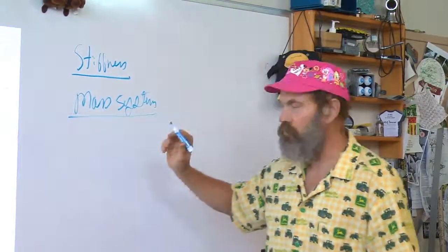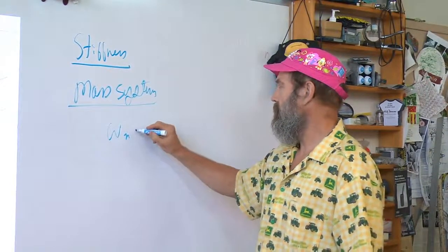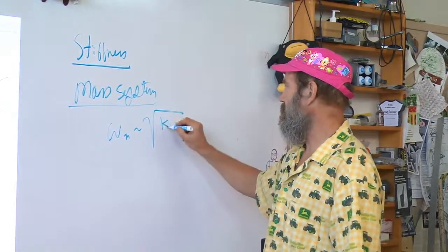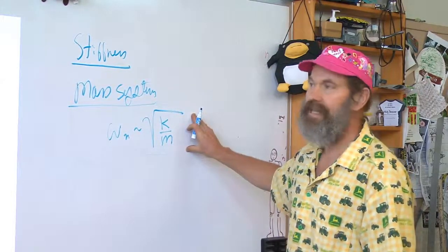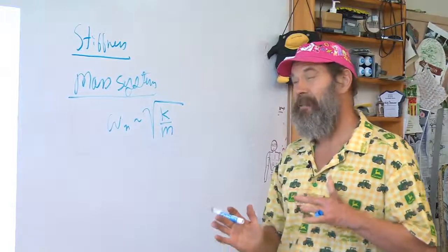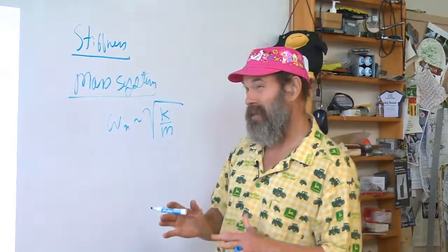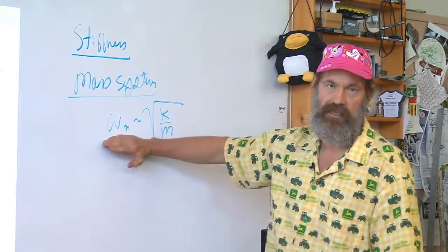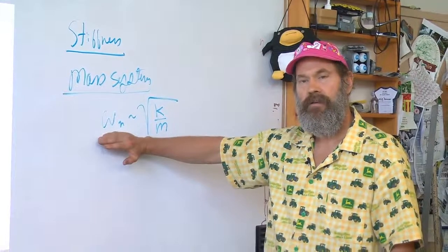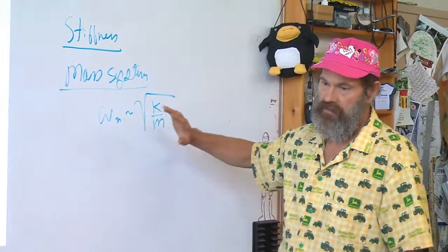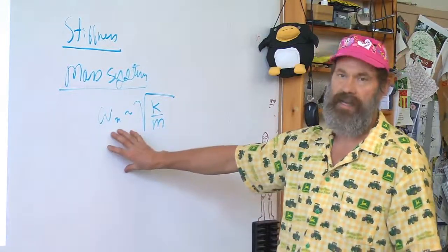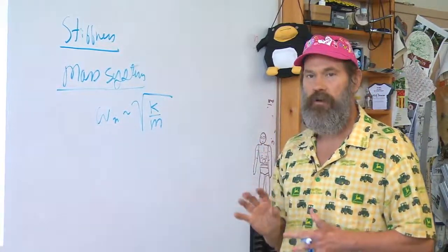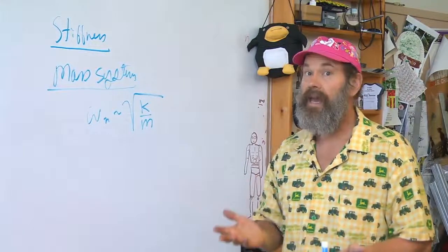So to our very first order natural frequency, going like the square root of k over m, for just very, very simple first mode guesstimates of, am I in the range of I'm going to have a problem or not? Well, it's going to depend upon what the excitation frequency is. And if the excitation frequency is either much less or much greater than the structural natural frequency, at least you have a hope of it being okay.